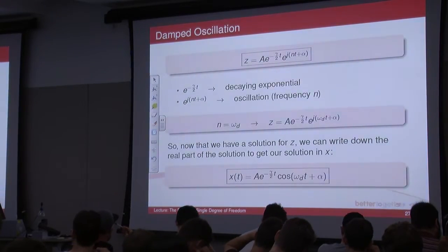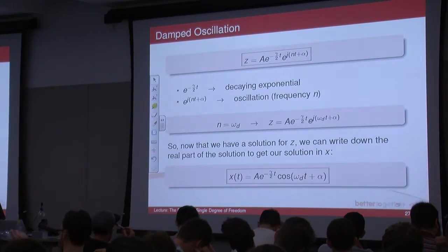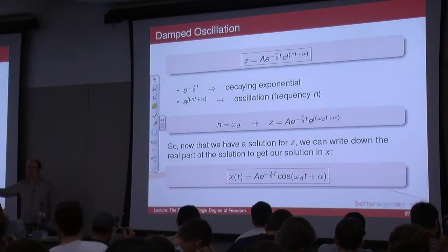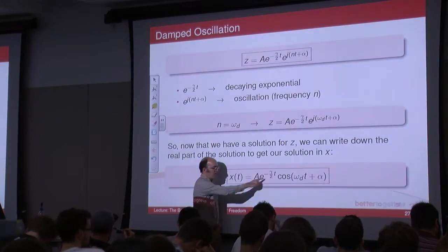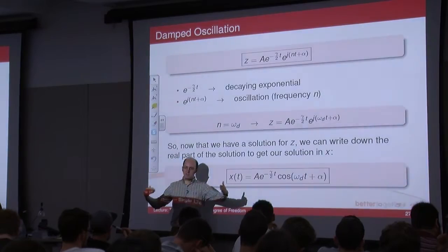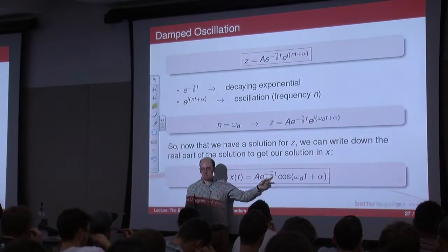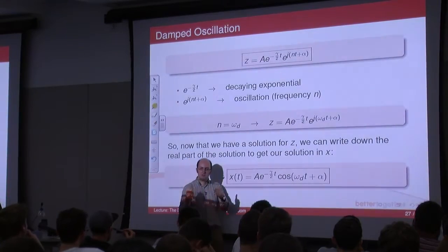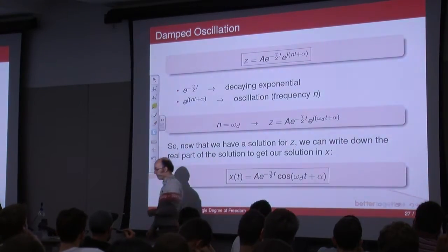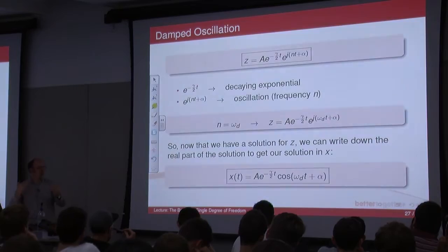And that decay will depend upon the gamma term, which is related to how much damping you've got. Low damping, it's going to take a long time to decay. Really high damping, you could end up with it not oscillating at all. If this is critical damping, you put it back, let it go, and the thing's going to move back and stop at 0. That's critical damping. Most systems are slightly underdamped, so it will overshoot and then come back. But how much damping you have determines how many times it overshoots and where it stops. And again, you'll come across this in control. Most systems are underdamped, so they'll overshoot and come back and then settle.